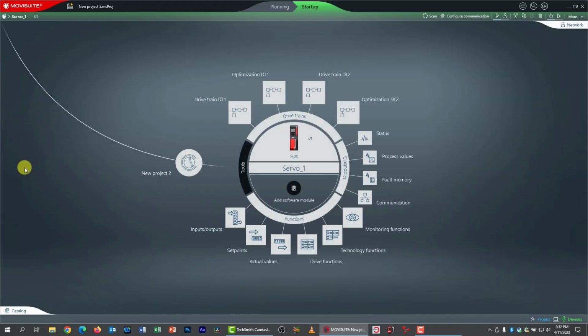Let's go back to the axis circle again. Now, all devices on a MOVI-C system have a status code of some kind. This is displayed on the front panel 7-segment LED display, but it's also available right here in MOVISUITE. There are actually 2 places you can see it. Let me point these out. First of all, if you go to the top quadrant of the circle, notice there's a little lone 01 here.